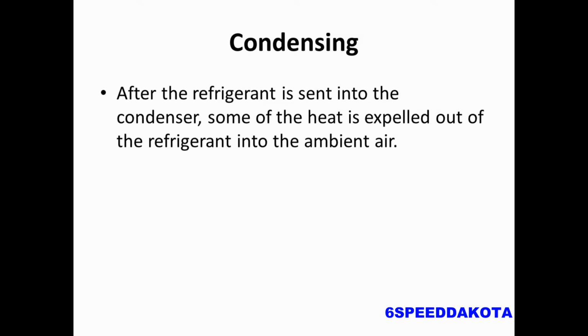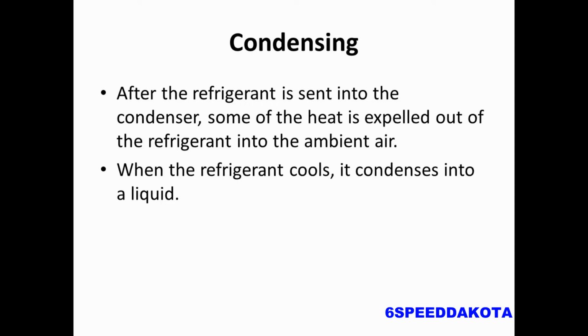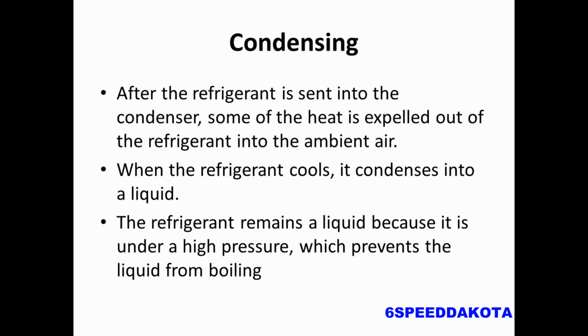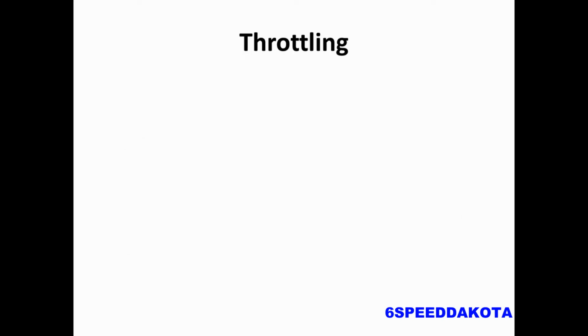So, condensing. After the refrigerant is sent into the condenser, it expels its heat out into the ambient air. When the refrigerant cools, it condenses into a liquid, hence the term condenser. The refrigerant remains a liquid because it's under a very high pressure, which prevents the liquid from boiling.